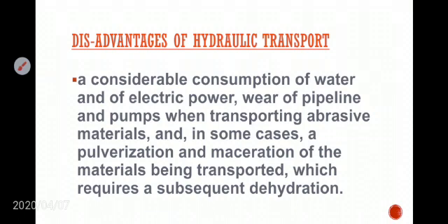That means when we transport heavy density materials through this hydraulic transportation system, obviously the pipelines may get damaged and pumps may also get overstressed and may be subjected to failure. So we need to change them. For that we need to bear some additional costs, and in some cases there is pulverization and maceration of the materials being transported.